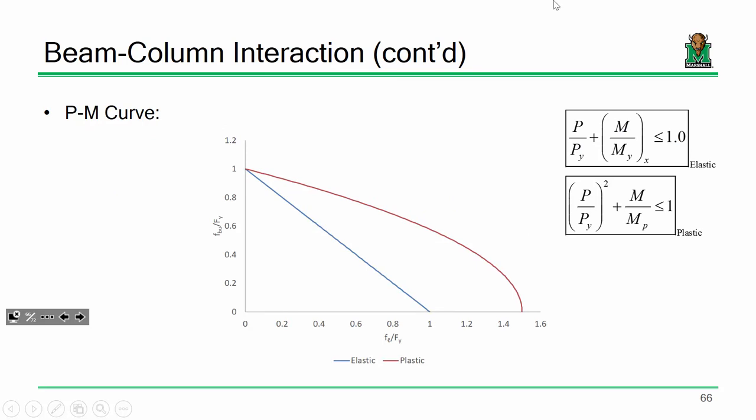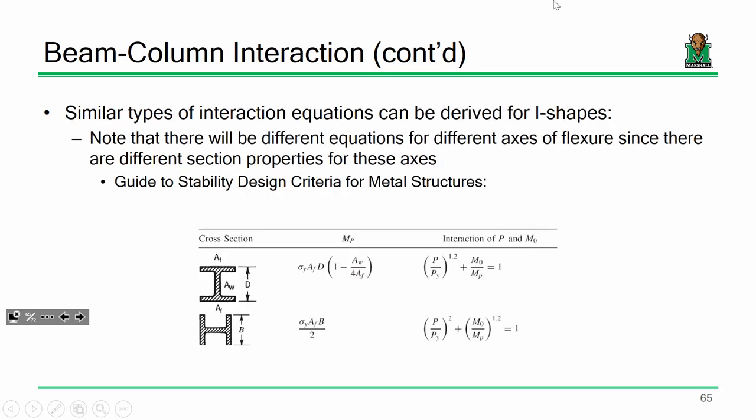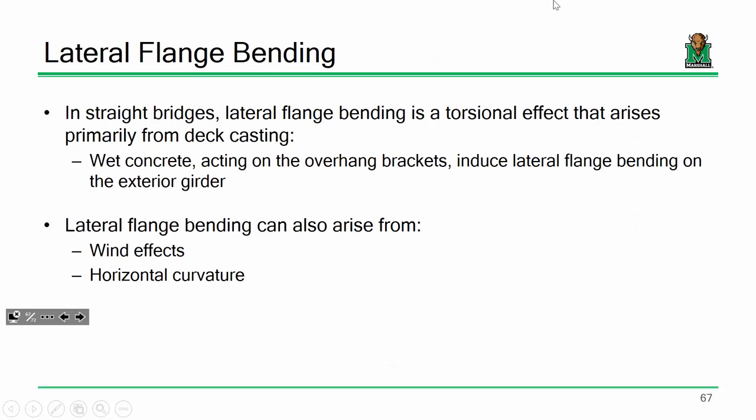So I propose that for a given flange made out of steel, a plastic interaction diagram looks something about like this. Elastically, looks like this. So far so good, and this is for a rectangular section. All right? And there's also, you can develop beam column interaction curves for all sorts of different sections. It's just algebra, arithmetic, and patience is basically all that goes into it.